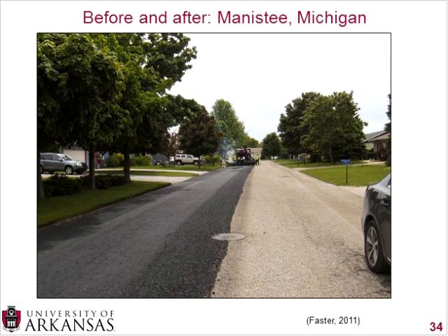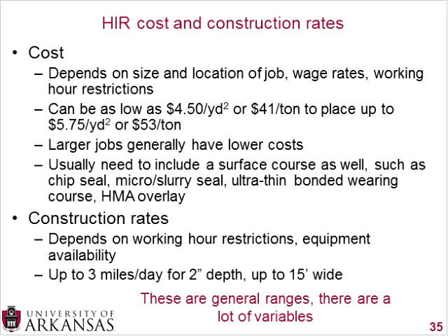And they probably used that scarifying technique where they're on the spring. So as you scarify that pavement and drag it along the pavement, it'll dig into the pavement. But when it hit that manhole cover, the springs popped it up and it was simply able to go over that manhole cover, which is a pretty convenient option, especially in urban areas where there's quite a few utilities.